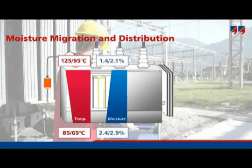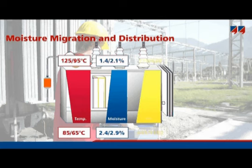The dielectric response method provided by Dirana will measure an integral moisture content. This means an average result. The degree of polymerization, or the mechanical strength, is typically worse on top of a winding than at the bottom. On top, the temperatures are higher, and so aging is much faster compared to the bottom.